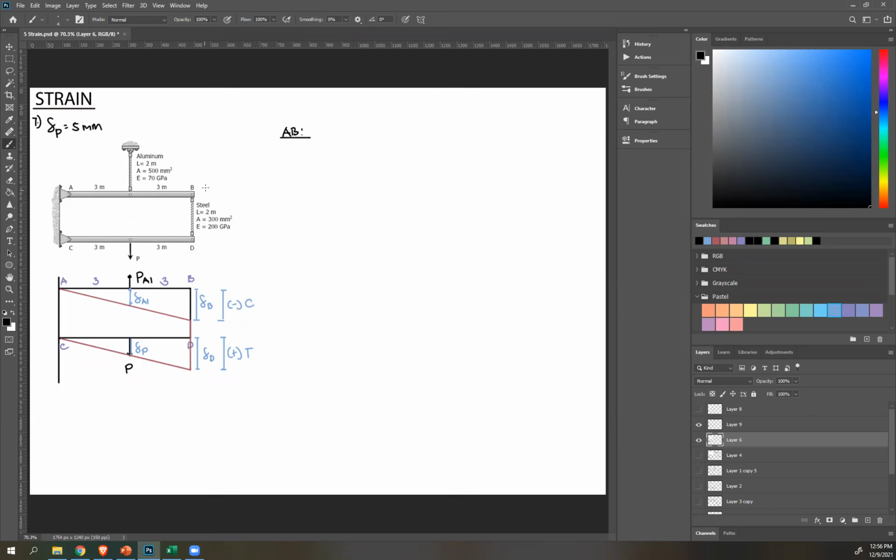Okay. So again, just looking here, bar AB, summation of moment. Previously we did it at the support. So same thing here, you're gonna do moment about the support here. Because this is a hinge, there's gonna be reactions this way or this way. I don't want to solve for that. And you don't even have to, because you can just take moment about A so that reactions cancel out. So moment at A equals 0. If you cut this part here, you can see that's PAL. Rotate about A, that's counterclockwise, so negative PAL, perpendicular distance 3.